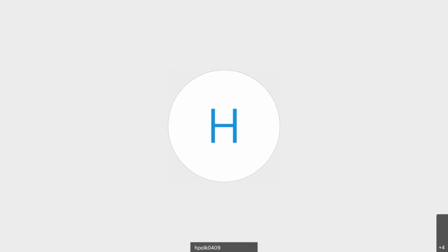And then I'll add that if you're going to use your screed assist, or if you have the ability to turn it on or off, you need to leave it on or you need to leave it off, in my opinion. If you start turning it on and off in the middle of a job, you're changing the gradation of that screed or that lifting force of that screed. So that was one piece of advice that I also offered. Just my personal opinion: turn it on in the morning when you start paving, and leave it on unless you're transporting the paver. At that point we advise turning it off, so there's no additional load shock or anything on the screed hydraulic system.